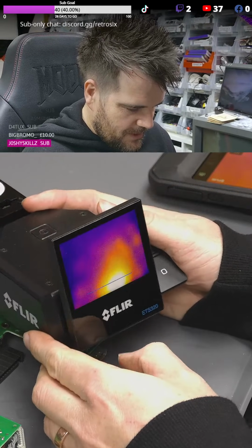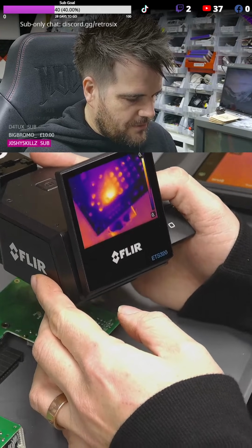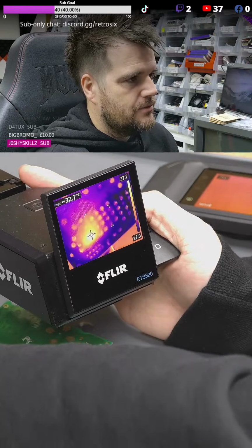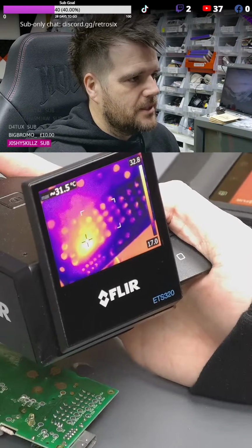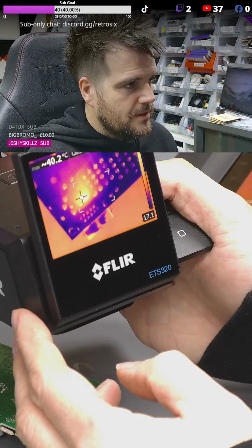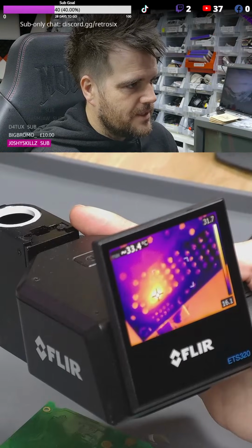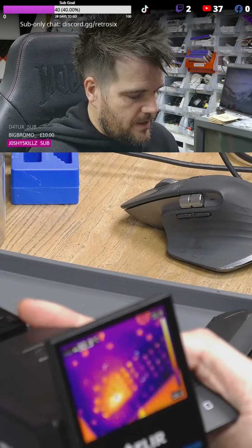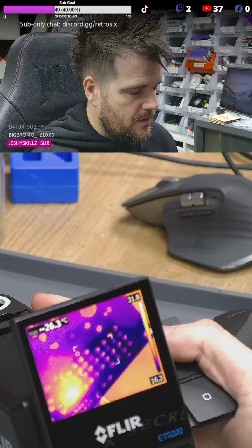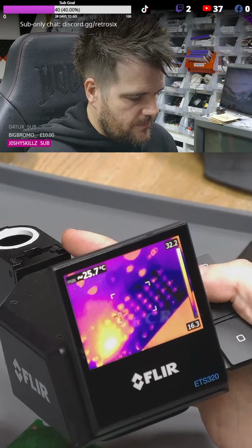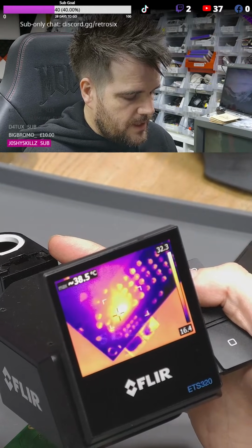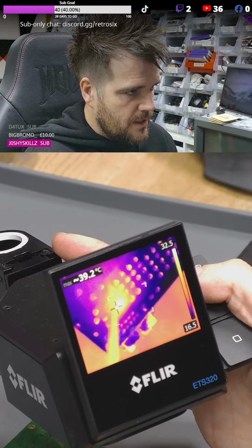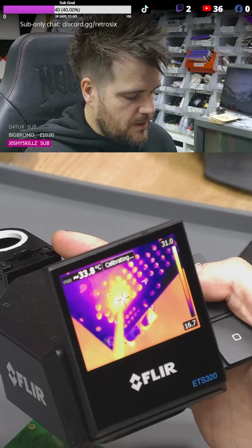So with a high quality thermal camera, if we get the focus distance right, then look at that. There's the difference in quality of trying to find where the problem is. So we bring the focus distance just right for this camera, and you can literally see exactly where the fault is. So get that in view. And now with that, I can move my tweezers in, and I can literally see my tweezers. I can see the shape of the tweezers. I can go directly over the blob.